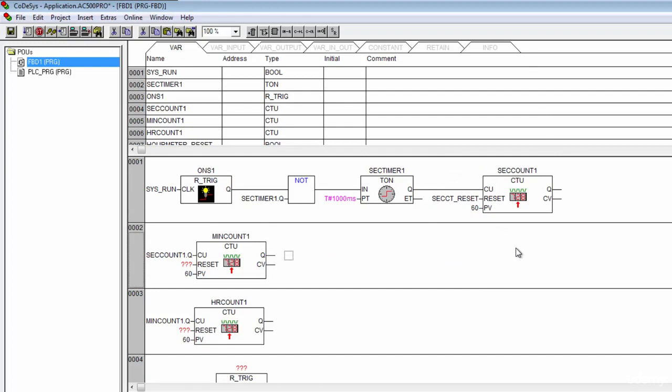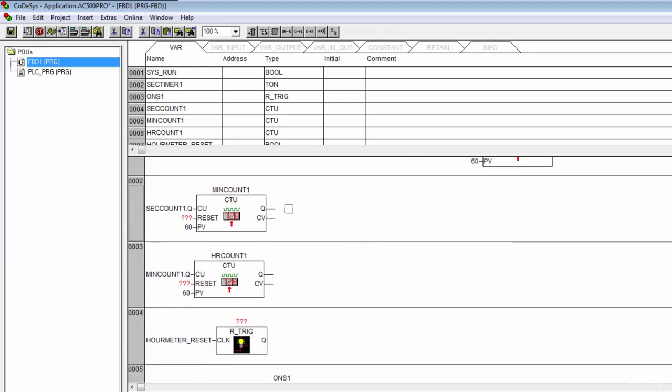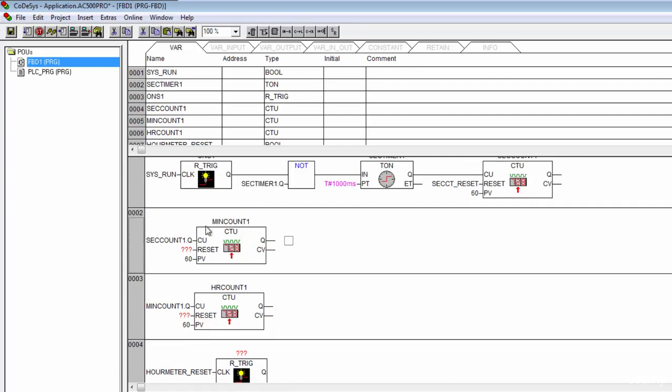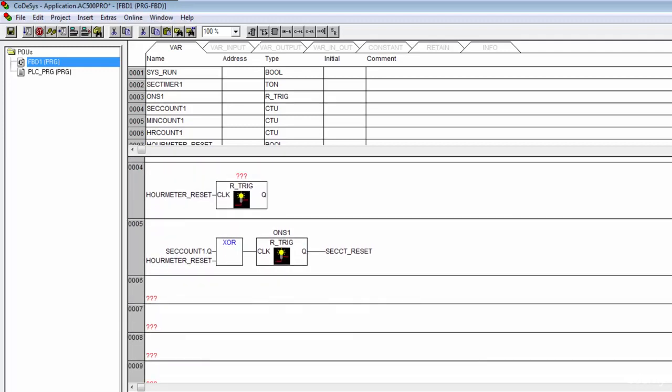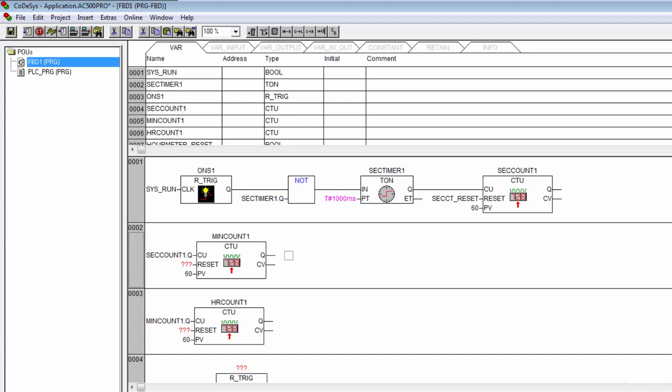So now we have two different ways to reset that counter, but if that expires before we start resetting things, we also want to make sure that we're looking at the accumulations. So sure enough, we're going to catch it right up here on rung 2, and then before it happens another scan, we're going to come down here and reset that. So now we've actually got one reset for one of those things. We need to create the same kind of reset for all of our other counters.